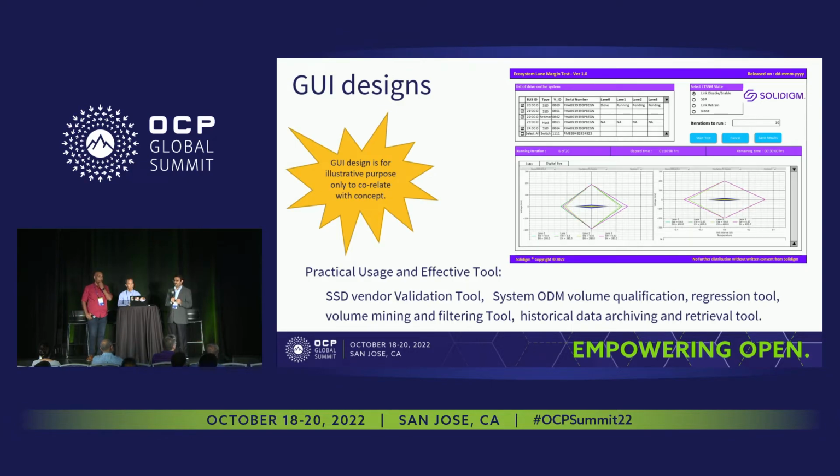So this slide is a pictorial representation of all these features I just explained. You can see on the left side the device tree, listing all the devices. On the right side, there are some LTSSM events. And when we run the margining, it should generate that kind of eye. You can see it's wide open, and it shows, yes, it's pretty good. And there is a mask provided in the middle that is based on the PCI guidelines, a minimum mask.